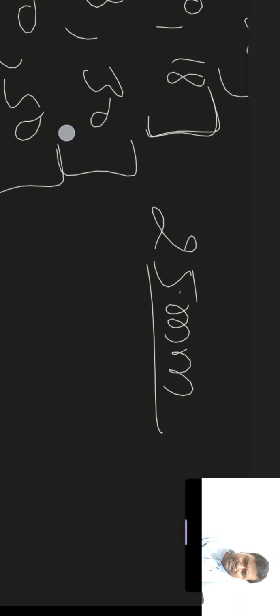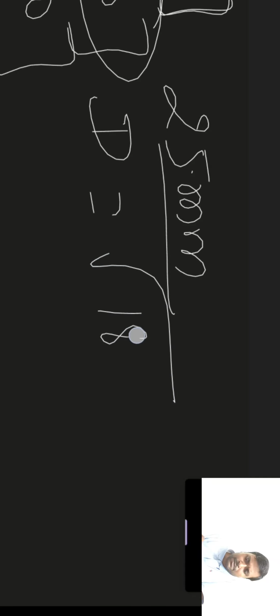You have studied in math, in set theory, what is the meaning of open bracket and closed bracket. We are not going into that. So next is 18 to 30, then 30 to 50. Suppose a shaft has a basic diameter of 25 mm. This will lie in the 18 to 30 range, and so the geometric mean diameter D will be root under 18 into 30.